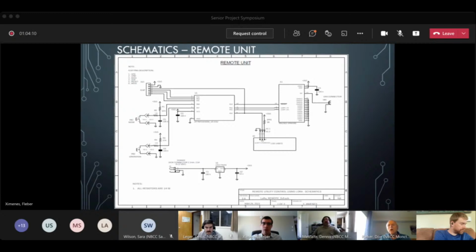That's why these LoRa and Bluetooth modules are becoming very, very popular. If you were to build the internals of this module yourself, you would have to go through all kinds of testing and certification from the formerly Industry Canada. But because the certifications are done by the manufacturer when you buy them, that's part of the price you're paying. As long as you follow their installation requirements, it will meet the certification requirements, and you don't have to buy it separately.